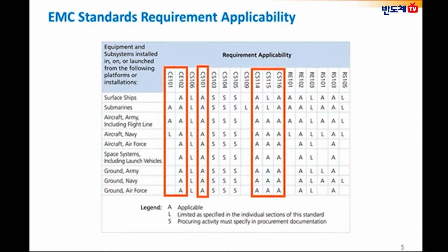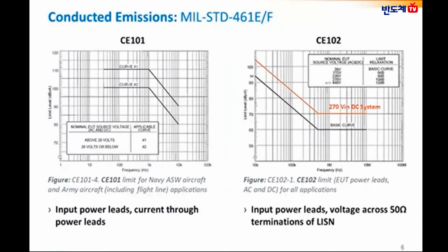Along with these, the environmental qualification requirements for switching power supplies are mechanical shock, vibration, temperature cycling, and altitude, which are documented in MIL-STD-810G. And most importantly, it is worth noting that not only the standalone DC to DC converter should meet MIL standard requirements, but also the overall system should meet MIL standard requirements.